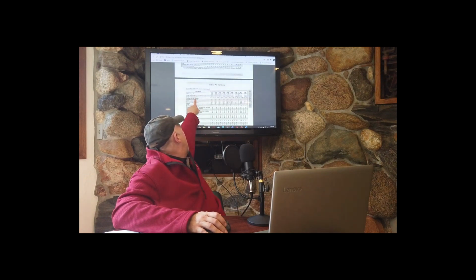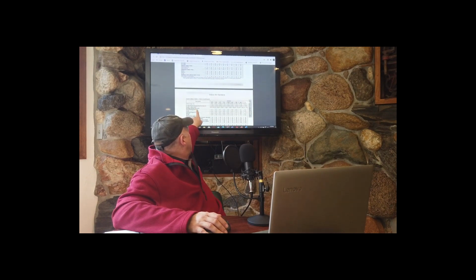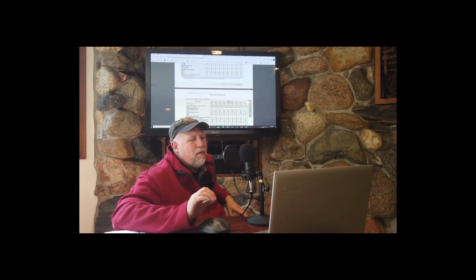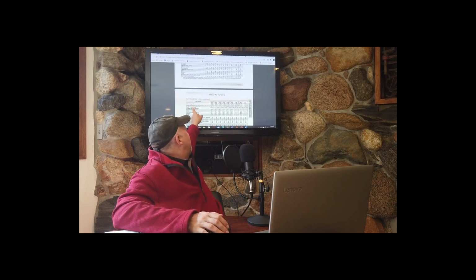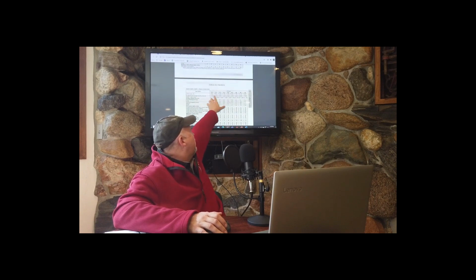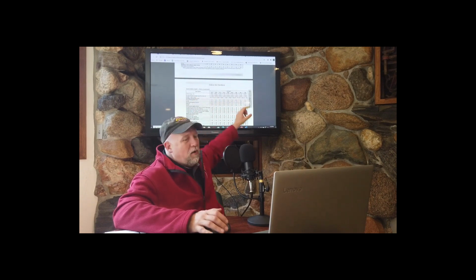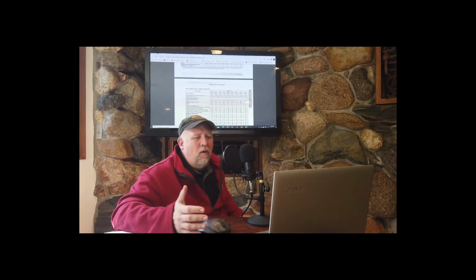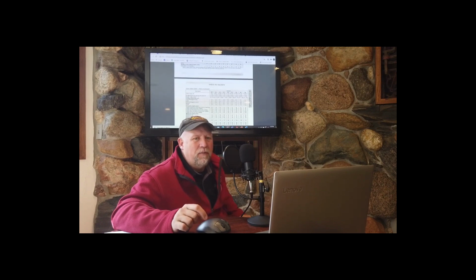And then above it, see where it says CFM at 500 feet per minute through the large face area coil. That is going to be the limitation on how many supply CFM that particular air handler can provide. Notice, if we look along this top line where it says unit size and CFM range, the airflow range, it can go up to 65,000 CFM, the unit size 090.